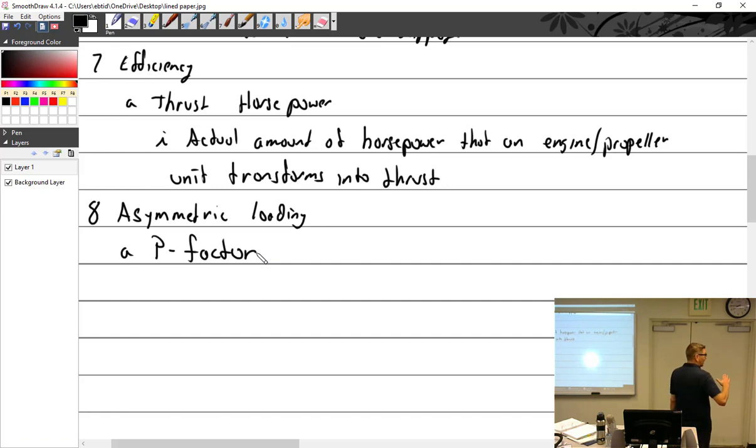So when you bring the tail up, it wants to go hard left. So you better be ready on that right rudder. This poor RAF pilot takes off in this airplane, brings it up, and he's thinking, I gotta be ready on the rudder. So he did. He brought it up and gave it some nice left rudder. Incorrect rudder. And that thing just went hard right out into the mud and flipped over on its back.